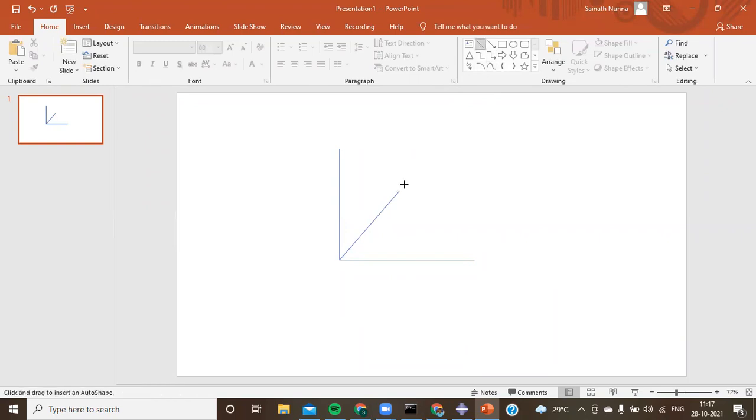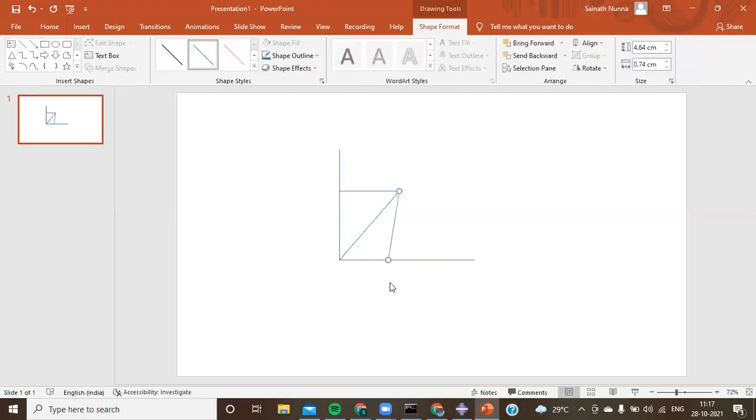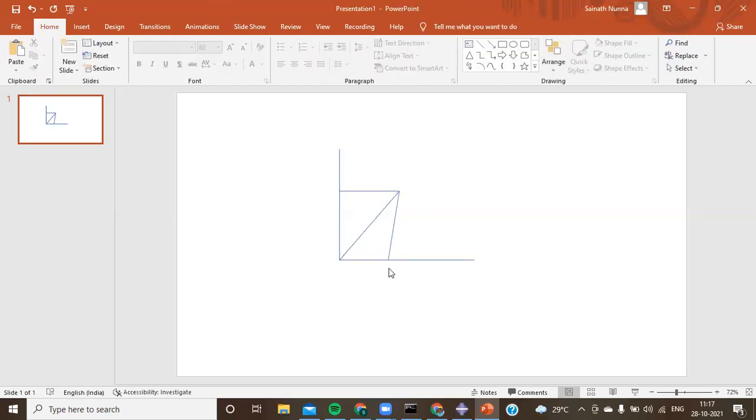So from here, I'm going to cut this, and I will say this is my yield stress. And from here, I can say this is something around a 0.2% strain by default for metals. Okay, so this angle is like 45 degrees.